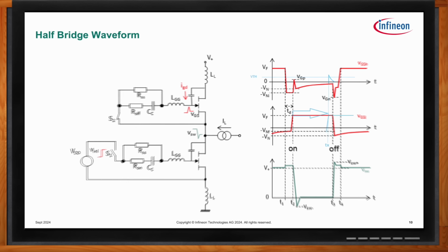Now imagine, due to a circuit operation such as an initial turn-on or perhaps in burst mode operation, for example, the bottom side gate turn-on was skewed as shown by the waveforms in blue. That is, we turn on the low side gate when the top side negative gate voltage has decayed to near zero. The resulting spike due to Miller effect, which we just covered earlier, could lead to the undesired turn-on in this case as well, leading to a shoot-through condition, which could manifest itself as increased switching power dissipation for the system, or in the worst case, it could actually lead to catastrophic failure.